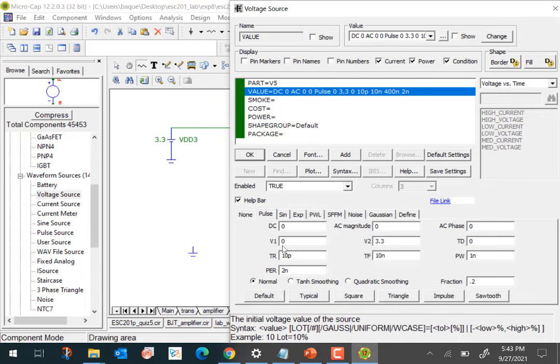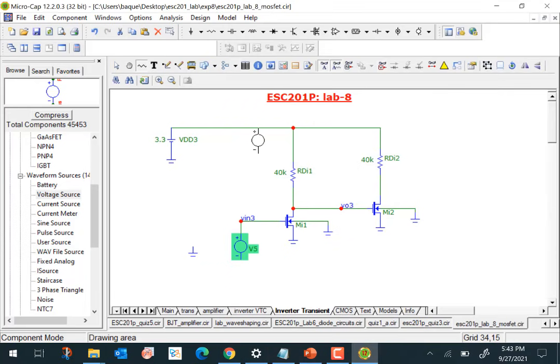So we're going to go from 0 to 3.3, rise time of 10 picoseconds, and fall time also 10 picoseconds. Pulse width of 1 nanosecond and period of 2 nanoseconds. We'll connect this to an inverter, and we have connected another inverter as a load for this particular inverter. Note that nobody makes just one gate, so you have one gate connected to the next and so on. So to make the simulation realistic, we've connected another inverter of the same kind as a load. We're going to look at V03 and V3 to see how the switching occurs.